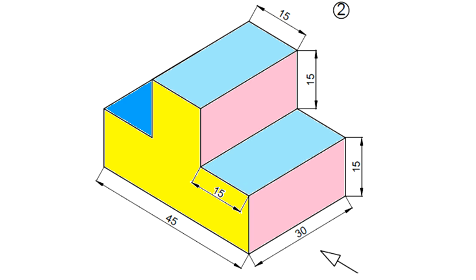For example, if for the same diagram they give the arrow mark here, how will the views change? If you follow the arrow mark here and draw, when they give the arrow mark here, then you will get 0 marks. So we need to see where the arrow mark is given, and you need to start the projected views from that point. Now they have given the arrow mark here, so this becomes the front view, the red color surfaces.